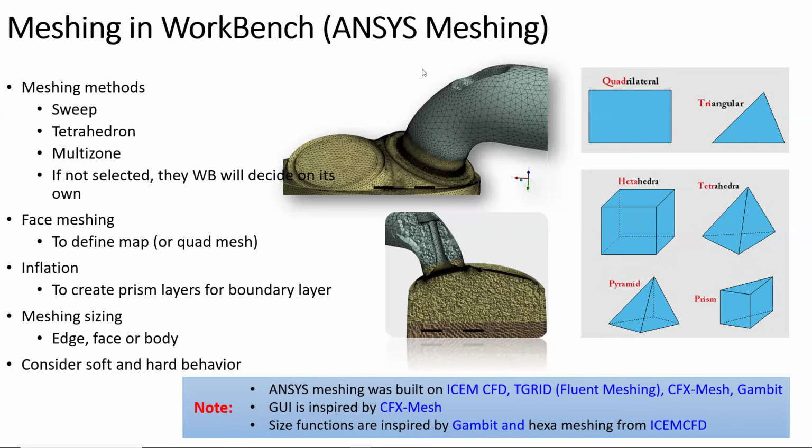In two dimensions we always go for the quad element. It's the best. And in 3D we always go with the hexa. Why? Because it has more sides. A quad element can get information from here, from here, from here, from here. So it can get information from the four neighboring cells. So we will be able to solve this mesh in less time, with fewer iterations. This will also have less diffusion.